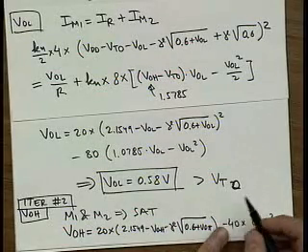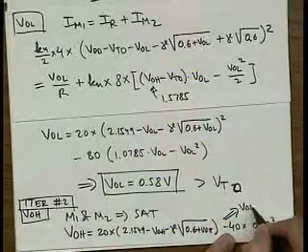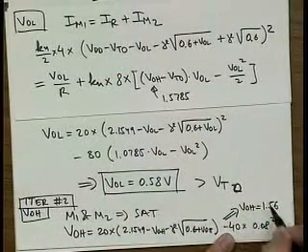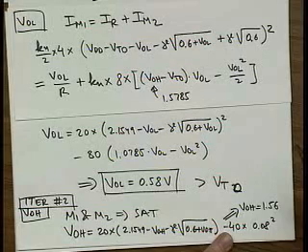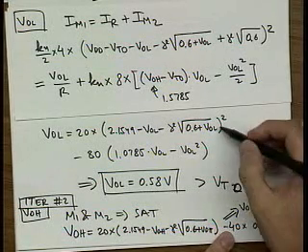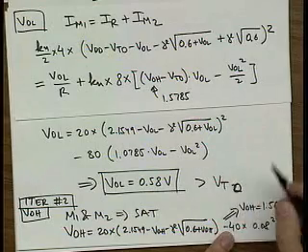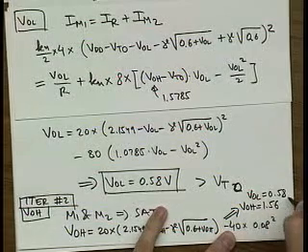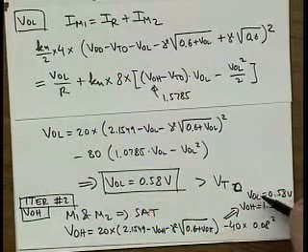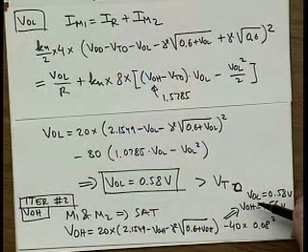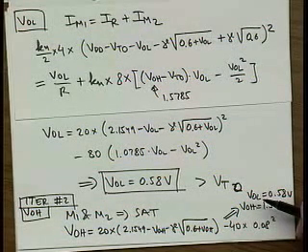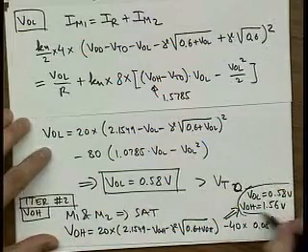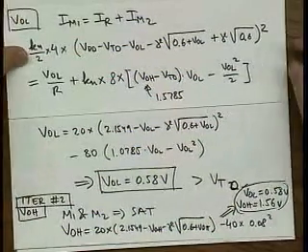And then when you solve this, you end up with VOH equal to 1.56, which is good because it's close to the previous assumption. You had 1.57, now you have 1.56, and then you plug that into this set of formulas, and then you get VOL equal to 0.58, which is sufficiently close to the first iteration result of 0.58, and then you're done basically. That's your answer. Now the question is, what is your VM?